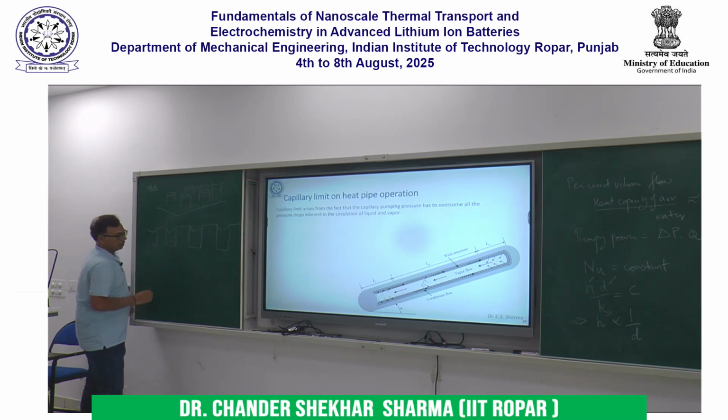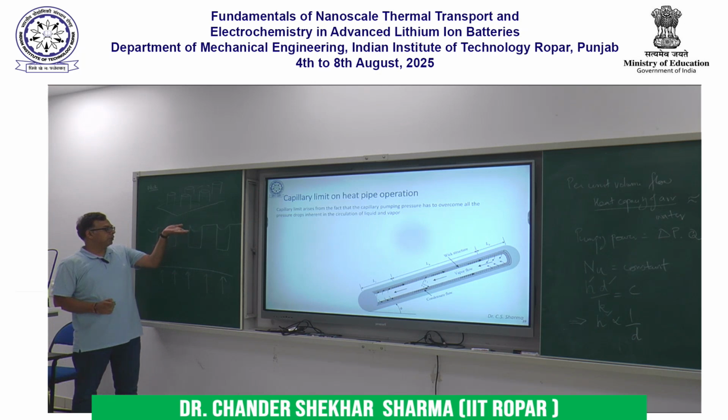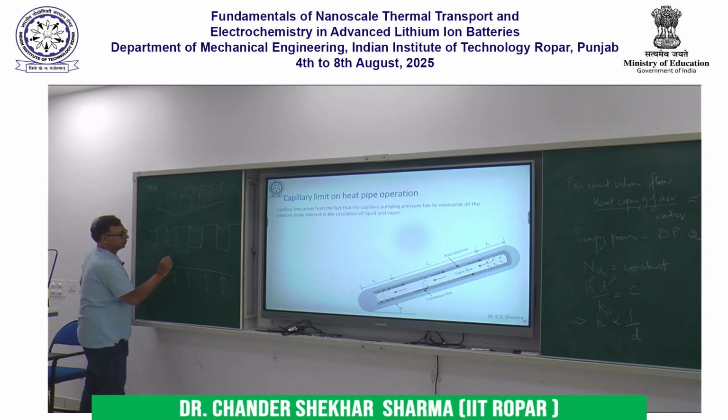Say now heat is coming from below. Now what will happen? This liquid will absorb this heat and it will start to evaporate. So liquid is evaporating, but it is also flowing along the wick, in this direction, through this array of channels of pillars.